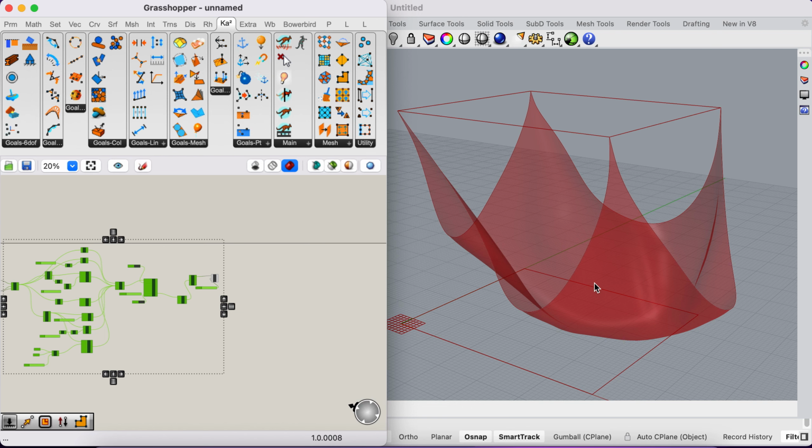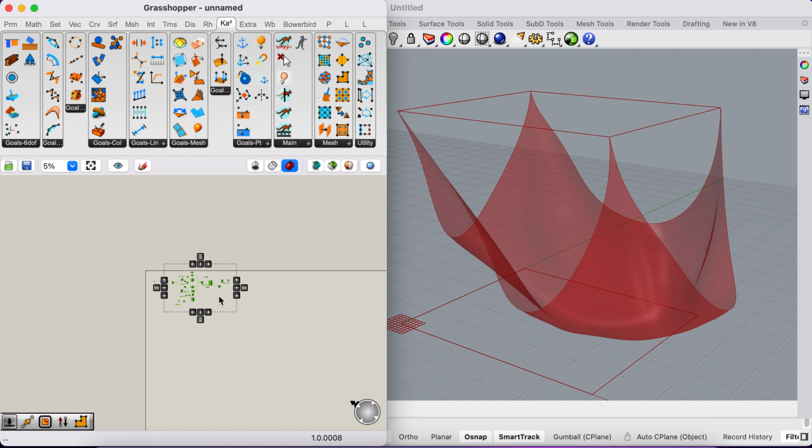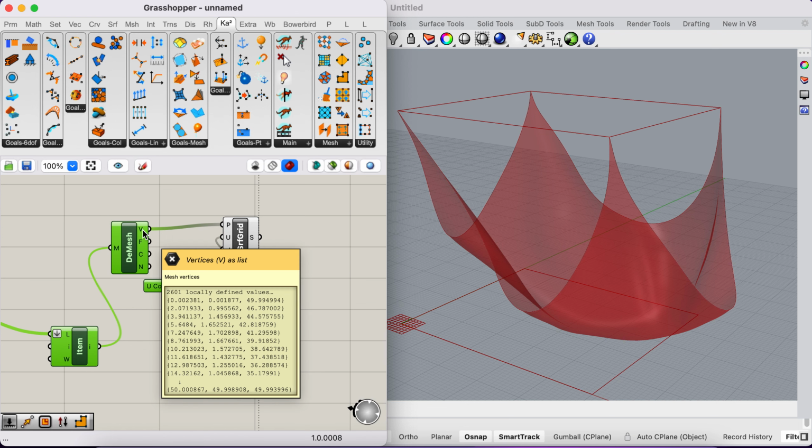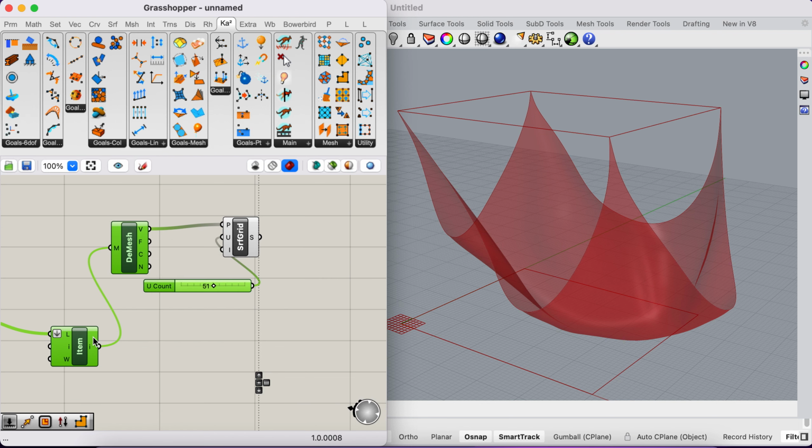So most of the time you might work with the surface grids, and then you get the error. Usually what you have to do is check the number of vertices and do the math to see if it is a prime number, that might be causing a problem or some other issues that you got. Okay, so all right, we got the surface now.